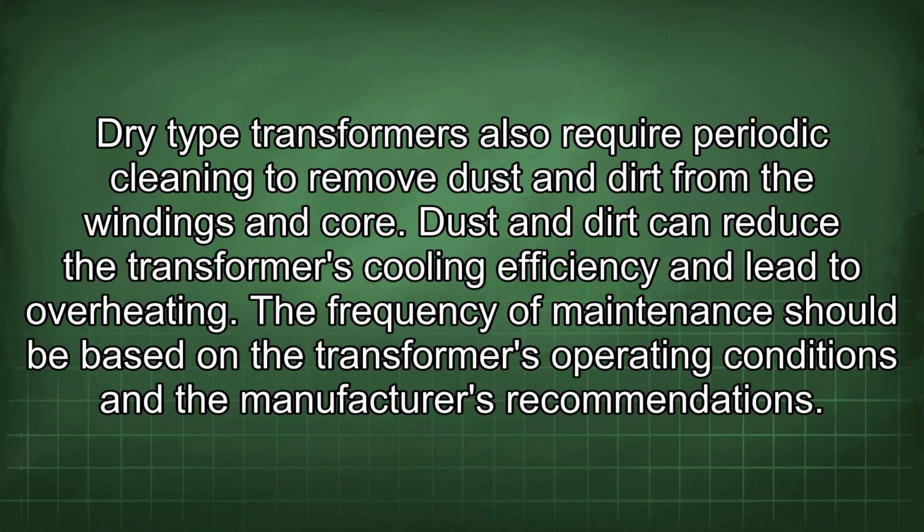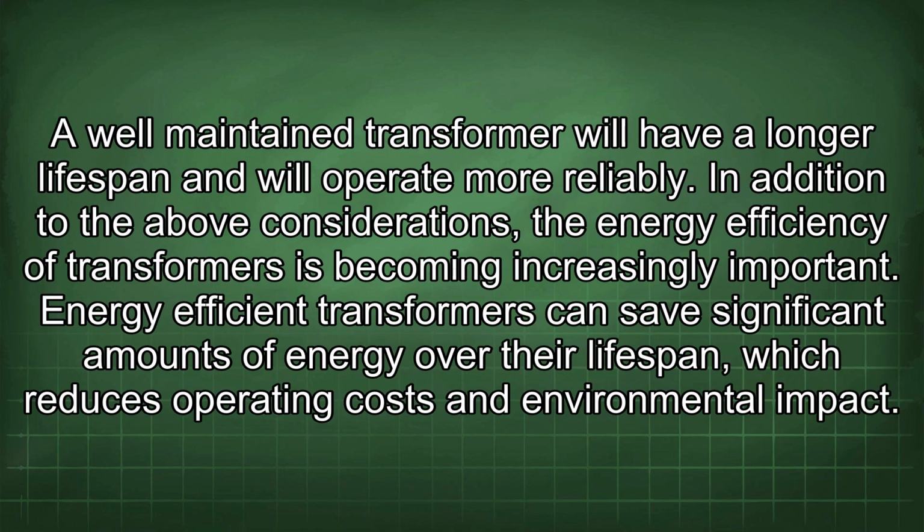Dry-type transformers also require periodic cleaning to remove dust and dirt from the windings and core. Dust and dirt can reduce the transformer's cooling efficiency and lead to overheating. The frequency of maintenance should be based on the transformer's operating conditions and the manufacturer's recommendations. A well-maintained transformer will have a longer lifespan and will operate more reliably.